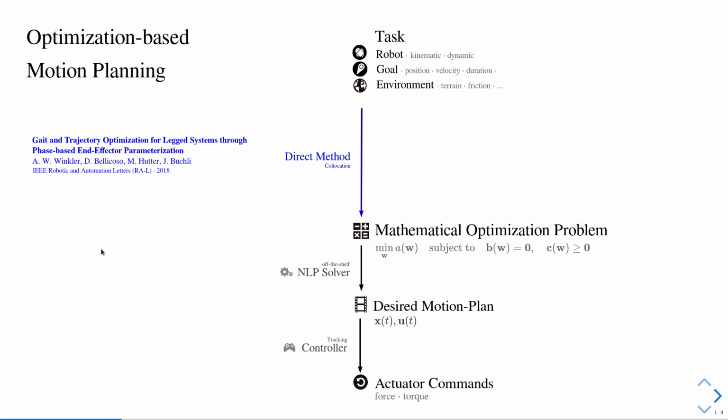To achieve this, we don't include a cost function, which often requires careful tuning of the weighting parameters to trade off between different objectives. Instead, we model the legged locomotion problem purely through constraints that have to be satisfied to create physically feasible motions. So strictly speaking, we are formulating a mathematical feasibility problem. And the entire rest of this talk will discuss those equality and inequality constraints.